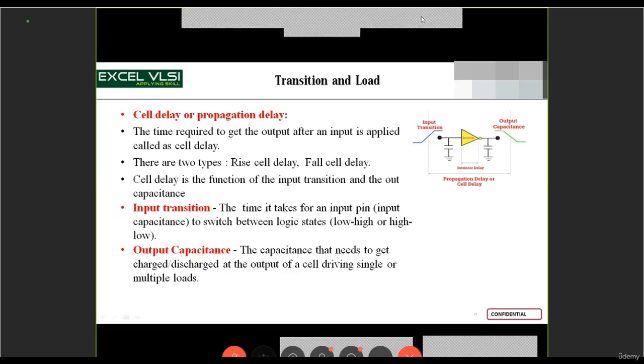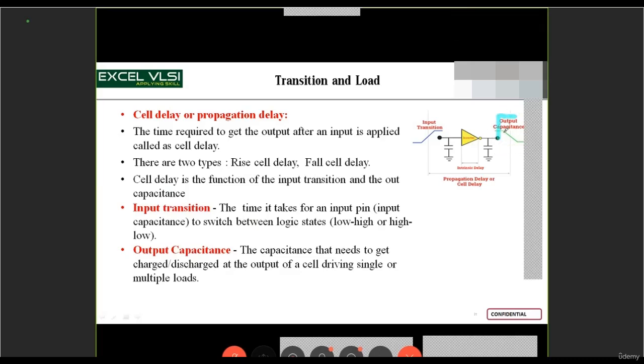So you are not sure, right? At this particular output pin, there might be a load, or there might be interconnectivity of other cells with one respective cell, or there might be multiple gates connected at this particular output pin according to the gate level netlist. So we take into consideration the capacitance values by summation of this complete load value, and the delay value is picked from the delay table.